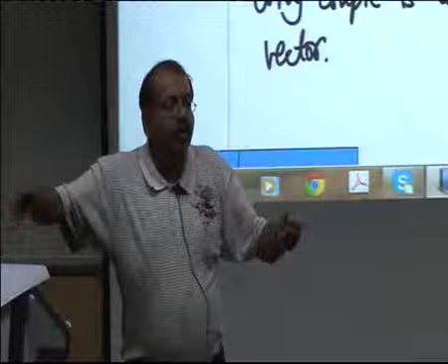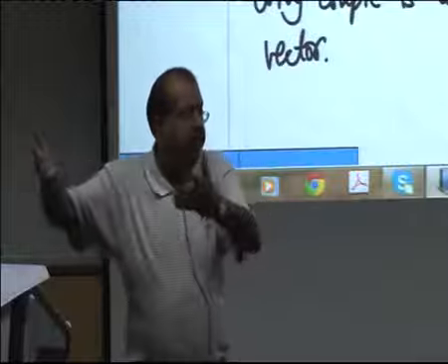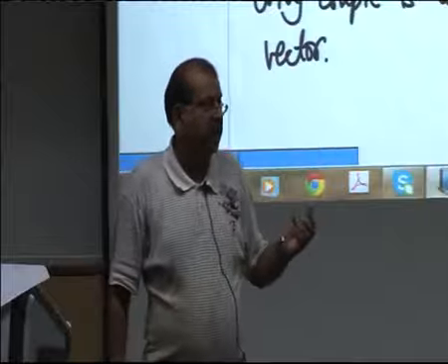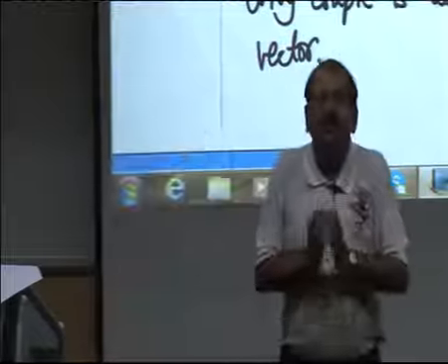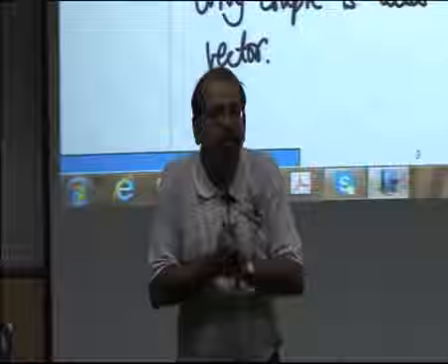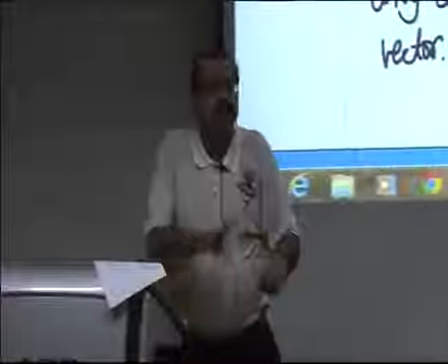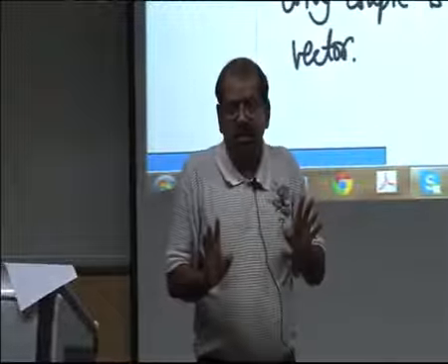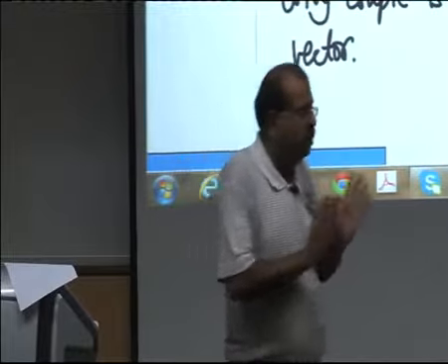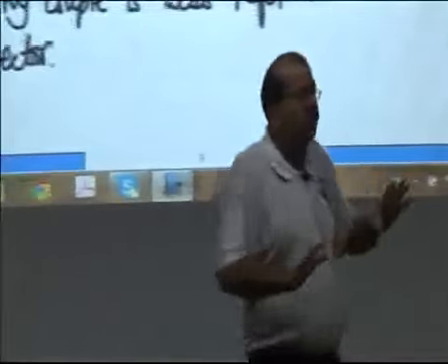You do it for all the forces, add up all the i, j, k components, and that will give you the final answer. In equivalent force problems, you will always find that you will have two components in the answer, a force and a moment. Is that fine?